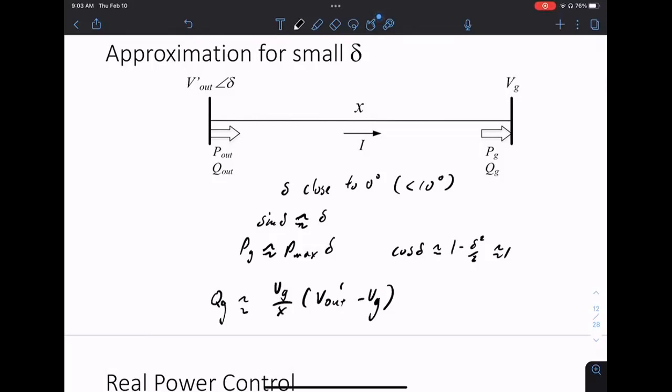Okay. And this again tells you it's very easy to make active power 0 and reactive power non-zero. I can make delta 0, and this thing has some number. That's why, again, a synchronous generator is nice. It has this sort of two decoupled control capability. Type 3 does not. You will not get this nice equation for type 3. You'll get this for type 4. Okay, so that's why type 4 is again nice. Questions?